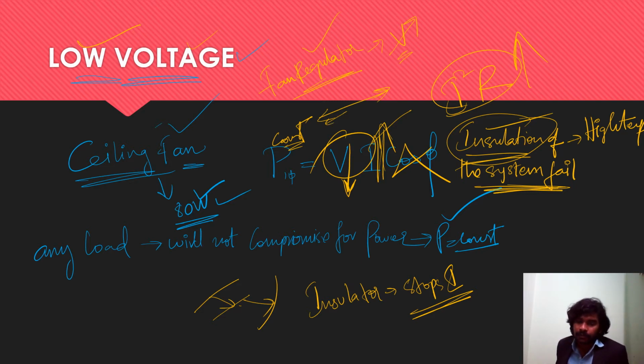If your voltage will dip or go down more than that, then current will be rising to an abnormal value, which leads to production of abnormal amount of heat and again failure of insulation. As electrical engineers, you know that low voltage will lead to high current in the system.